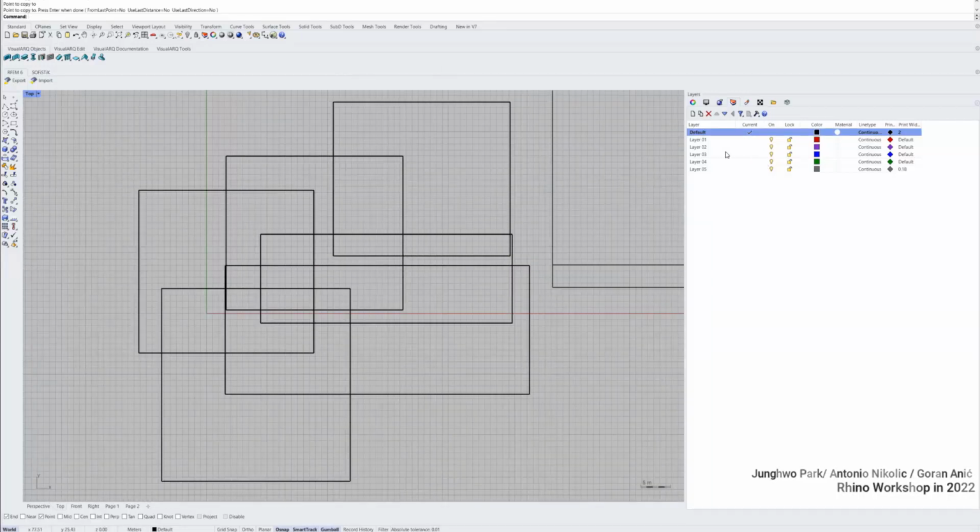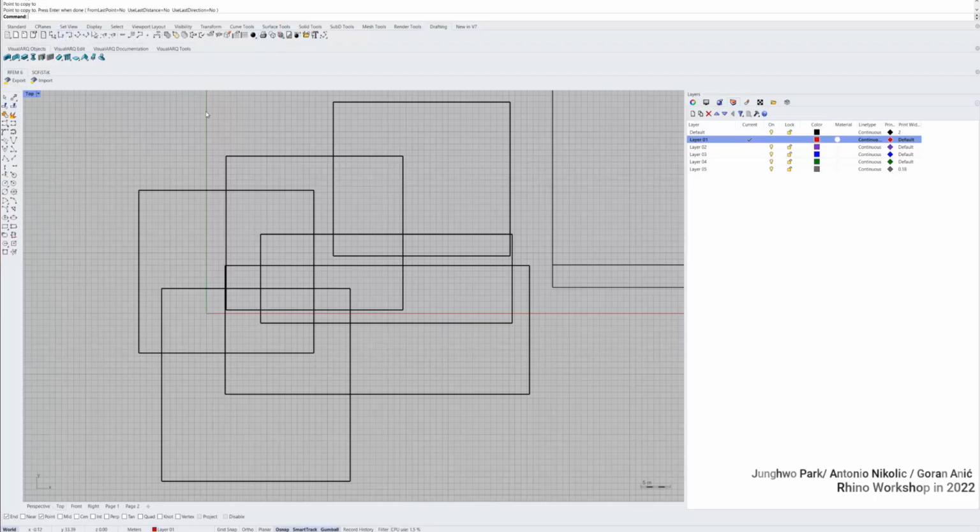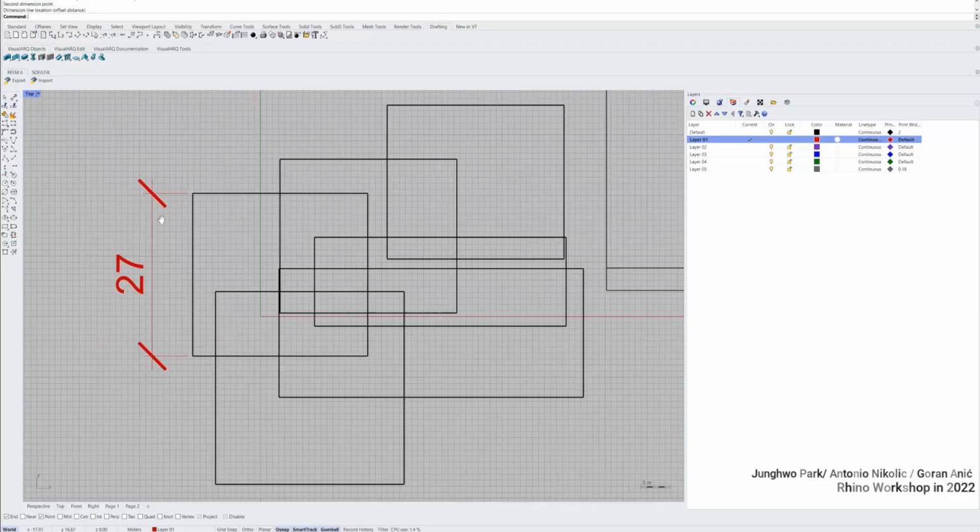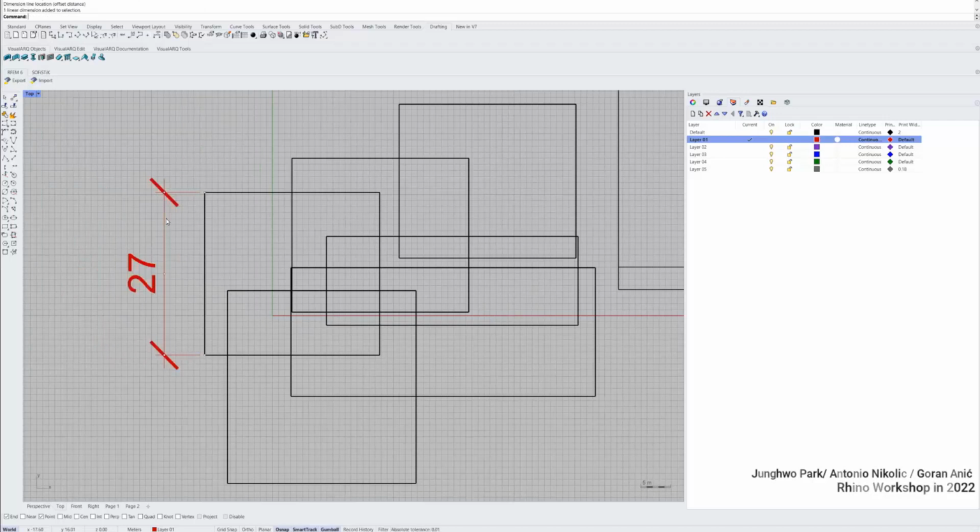You can also put the dimension. So I'll double click on layer 1, and when you go to drafting here, section, as you can see we have so many dimension tools here. Or if you type the command word dim, there are all the dimension options. For example, dim aligned, and I can put here and there, and you can get the dimension. I'll do one more time. The dimension style will use meters architectural, but you can make your own dimension style.